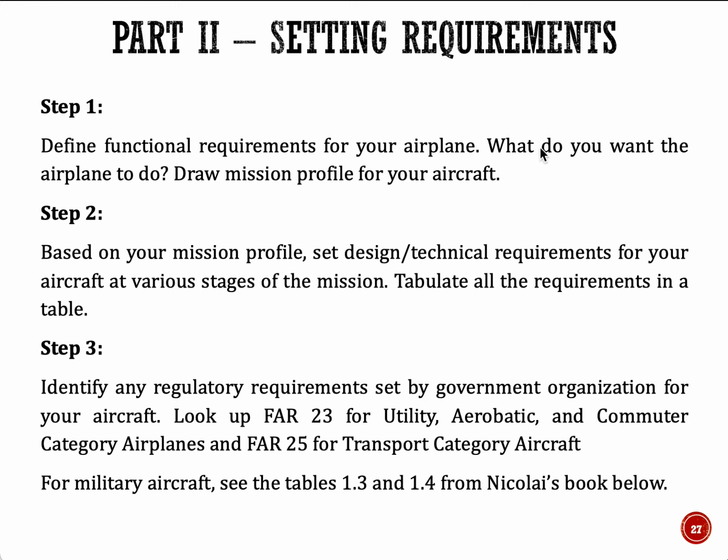Basically, you'll be determining what you want the airplane to do, and you'll be drawing a mission profile for your aircraft. Step two: based on your mission profile, set design technical requirements from the historical data, right? You use historical data to do it for your aircraft at various stages of the mission. Tabulate all the requirements in a table for different mission specifications, right?